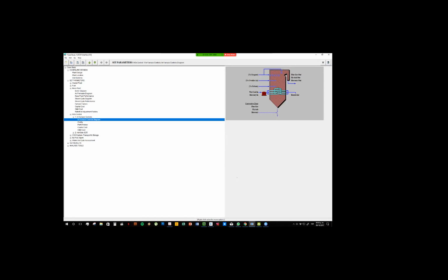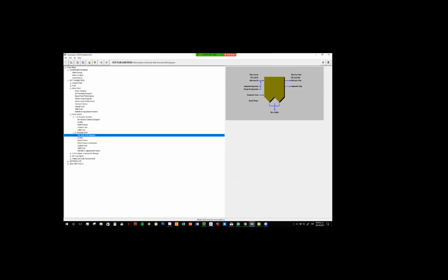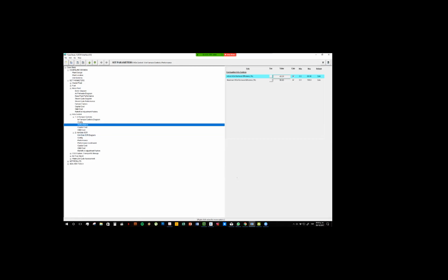But if you need high temperatures, you're going to produce NOxes either way. So that's why we then have a hot side SCR. In this case, it's going to treat the NOxes with ammonia and water vapor. I'm not going to go deep into that one because you have to research it for an activity that we're going to do.